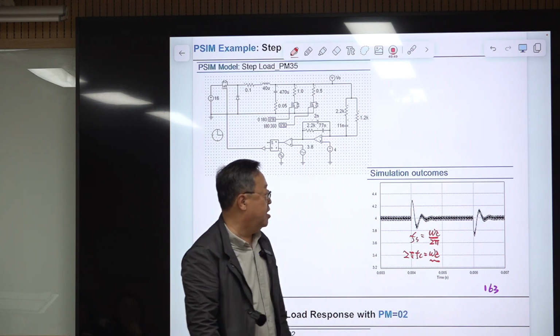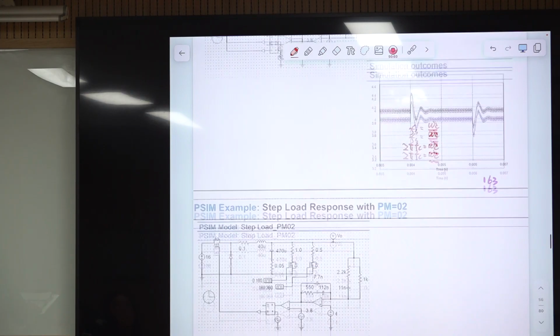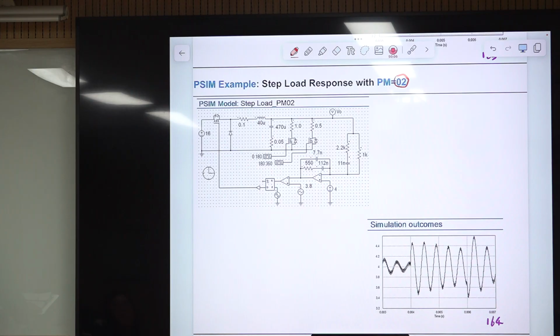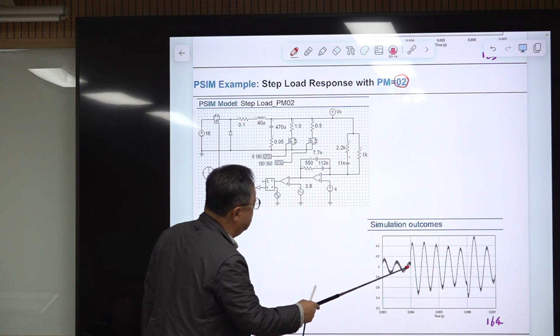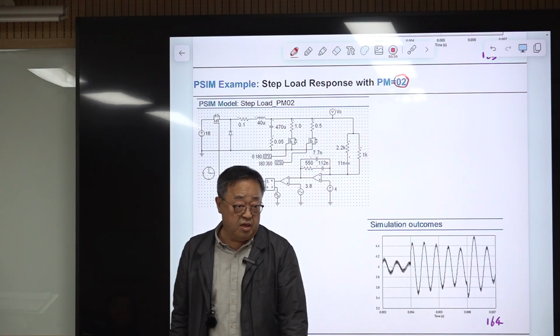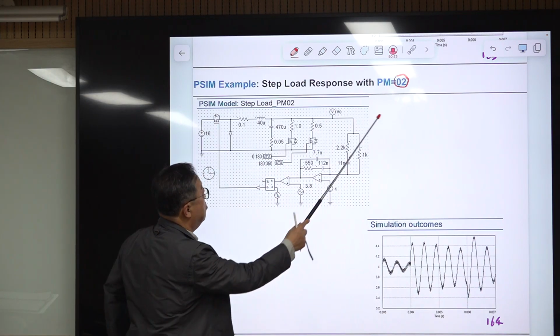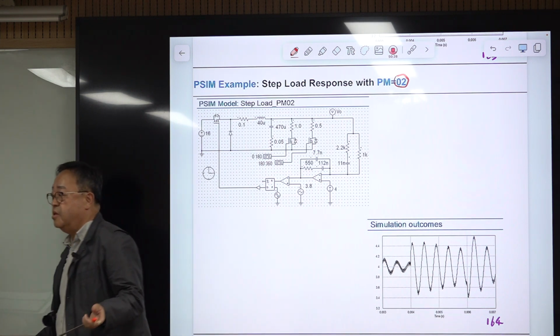All right. So there are two types of knowledge here. You can obtain the peaking frequency and crossover frequency from this plot. And I further reduced this to get an almost unstable system. Then output voltage is crazy. It was trying to settle down, but at a disturbance it goes up and something like this. This is an almost unstable system, very small phase margin. So it cannot be accepted, right?